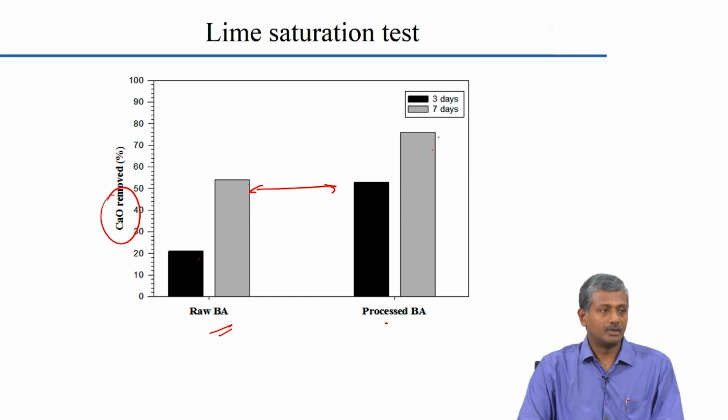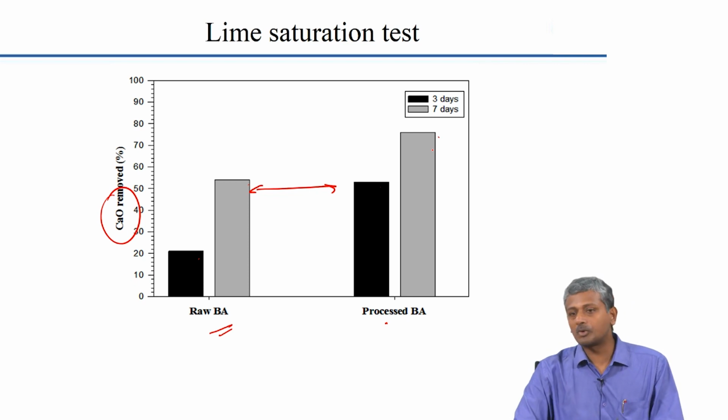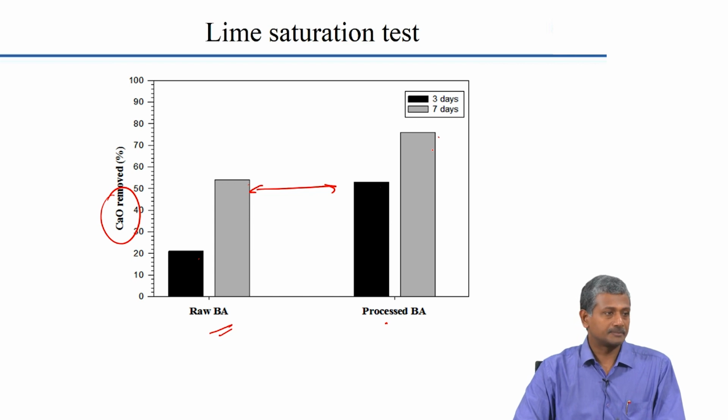actual concrete. So, all these tests, please remember, are done either on cement paste or mortar. So, the amount of test time and material is reduced significantly as opposed to doing tests directly on concrete. Wherever possible, if you can devise your test methodologies to work at the cement paste or mortar level, it helps in reducing the time it takes to proportion your concrete properly.